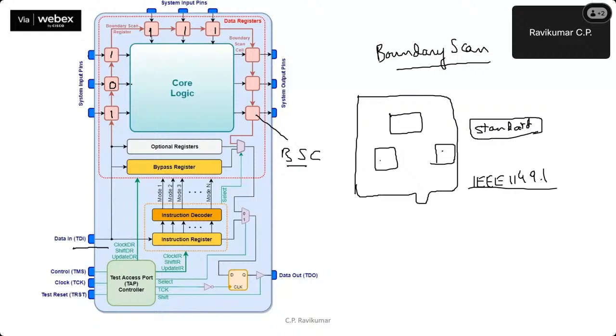As a matter of fact, there may be a scan chain here. So I may be able to use this path to initialize a scan chain, and I may also be able to initialize all the inputs. Once I have done all that, I can go into the normal mode of operation, and allow the circuit to produce the correct response.